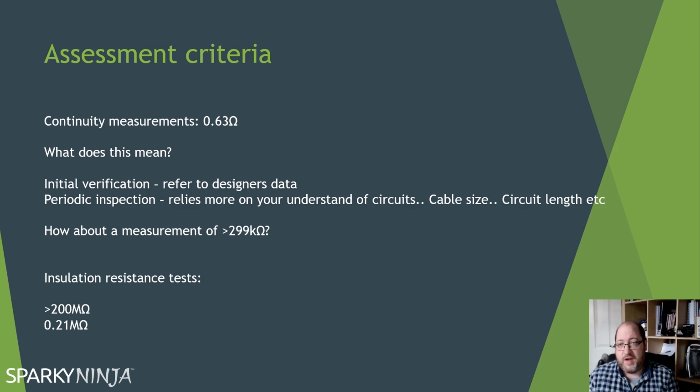If I had a 2.5 cable that was of a sufficient distance, then fine. But I know where I can go for the data. If you look in the back of the On-Site Guide or the back of Guidance Note 3, there are tables, resistance of conductors in milliohms per meter. The more you do testing, the more you'll understand how resistances go up as you play with cable sizes and length. But develop an understanding of that.